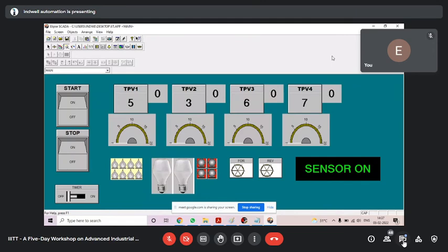Yes, Tanish. Scaling was for accumulator and preset. Why? Because these accumulator and preset we have from Mitsubishi. In Mitsubishi, timer, accumulator, and preset is multiple of 10. That's why we have taken. If you will take counter in Mitsubishi, counter is not multiple. So counter we don't need to scale. So whenever you have to scale your numerical value, you have to use scaling.